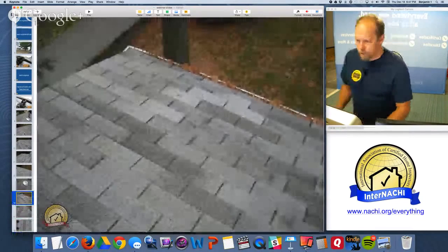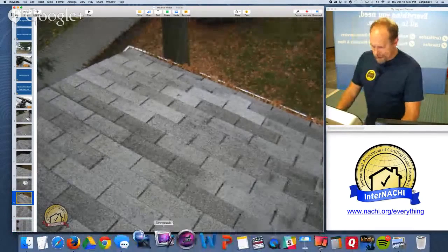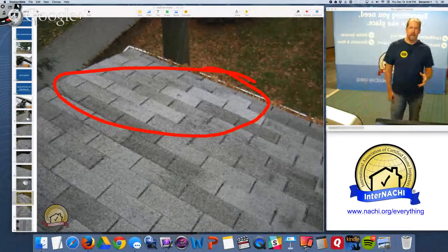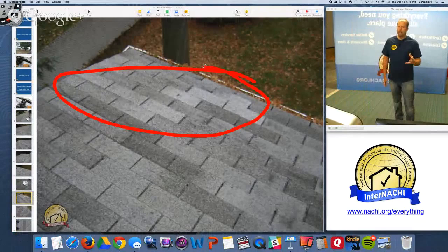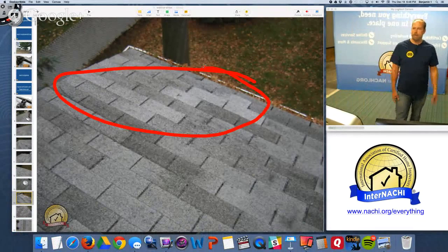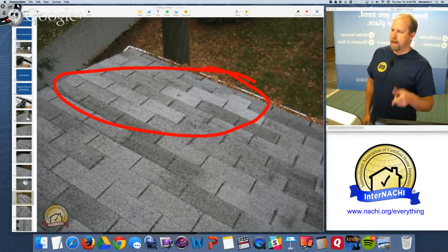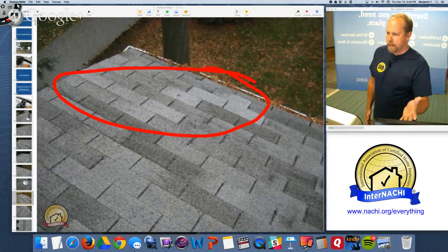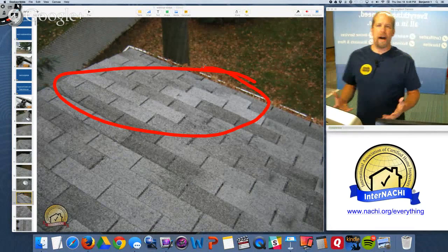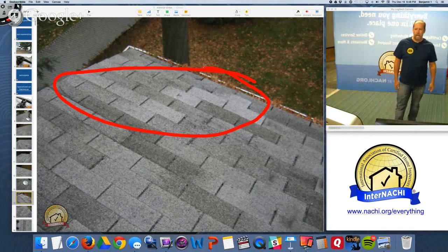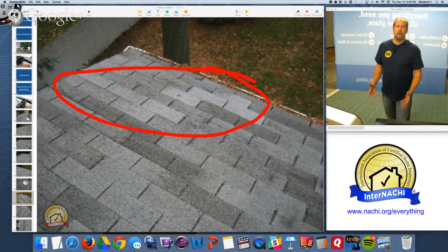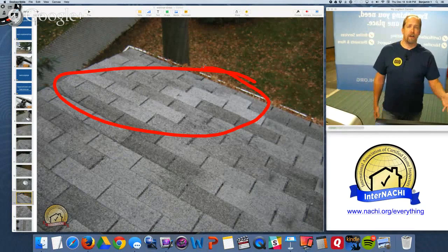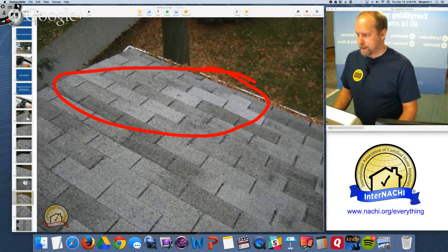And yeah, right here, let's see if I can use my tool. There it is. So I have a few shingles that have been replaced. It looks like some of the tabs, some of the shingles have been actually replaced. It could have been that tree nearby, a lot of leaves, maybe some ice damage. Looks like some scuffing from someone making repairs there. I don't know what's going on, but I identify anomalies like that to my client. The front right corner of the main house shingle roof may have been repaired in the past. Ask seller for more information. That's basically what I say.